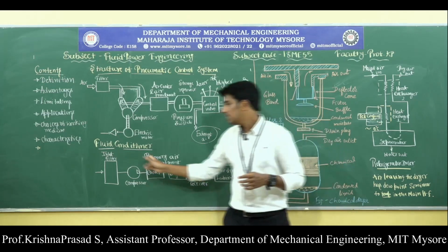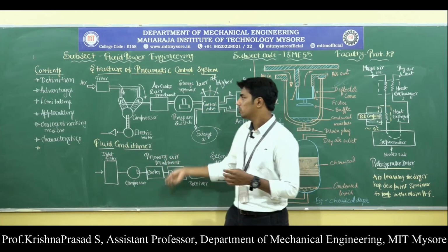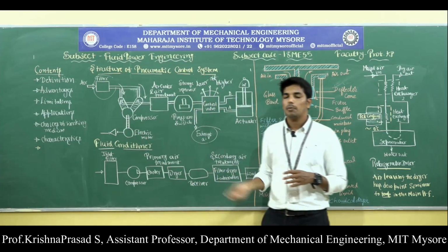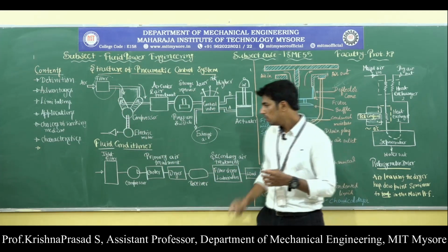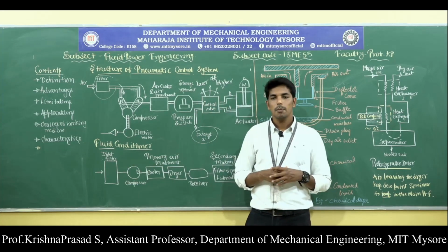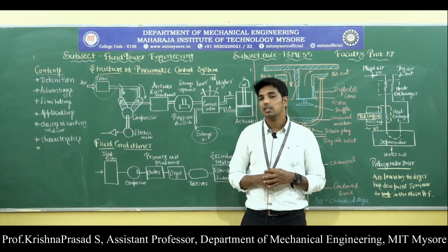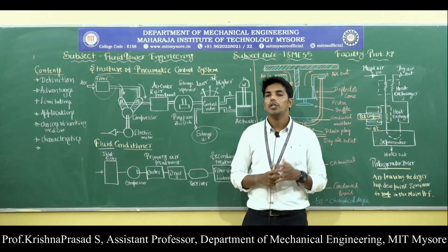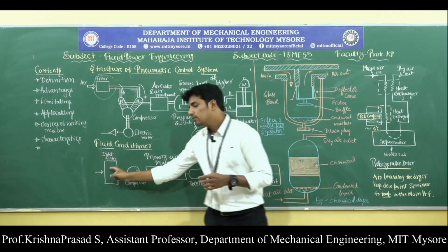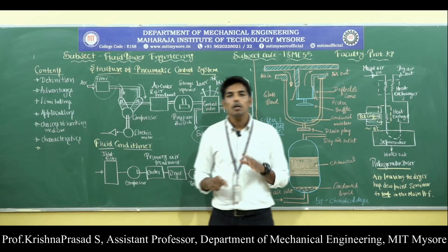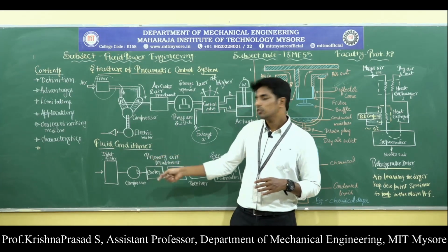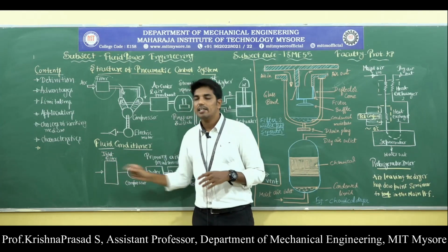So what happens in case of the filter? That is very important. We are going to explain this part through the fluid conditioner, or preparation of compressed air. Initially, the inlet filter arrests suspended particles like dust particles, because these would affect the parts of the compressor. So first, inlet filtering removes the suspended particles which can affect the compressor.